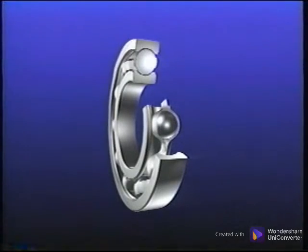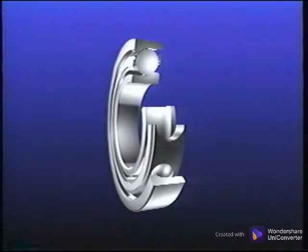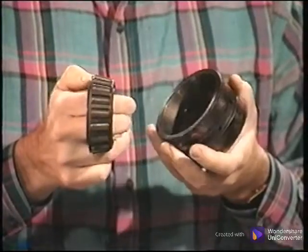The contact angle is 0 for bearings that do not have any thrust loading, such as this ball bearing. This angular contact ball bearing has a contact angle of 30 degrees. It is measured from the center line of the balls to the center of the curve. It is important to know the exact contact angle because the calculations vary with the angle.